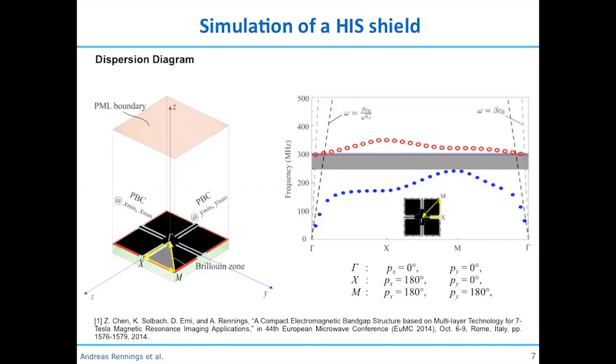And within this dispersion diagram, all the information is included. As I mentioned, the phase shift is given, and the resonance frequency is calculated. So that would be the eigenfrequency of the corresponding eigenmode. And here you can see essentially two modes, the blue one and the red one. The blue one starts here already for very low frequencies. It's a TM-like mode. It's mainly concentrated here in the dielectric. You can see it here.